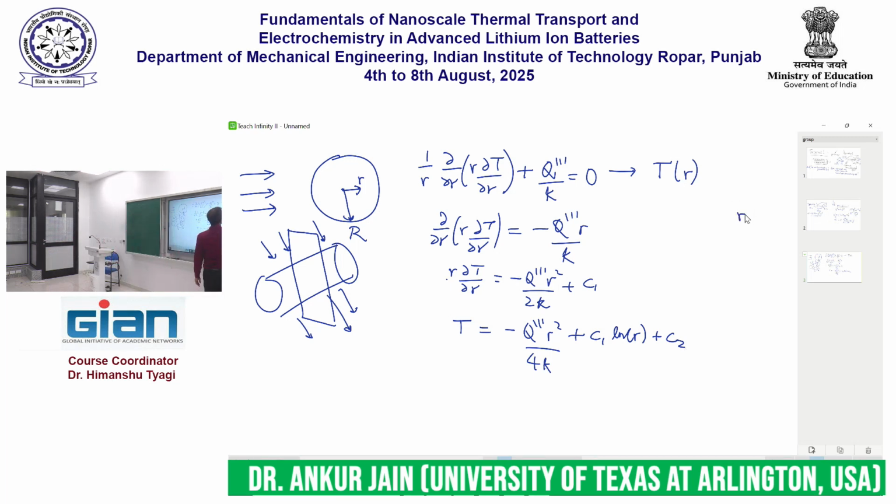So I need to write some kind of boundary conditions at r equals 0 and at r equals R. At r equals R, the simplest boundary condition to write is that the temperature of the cell will be exactly equal to T infinity. The air that is blowing over it, if it is going to cool down the cell perfectly, then the outer surface of the cell will become T infinity.